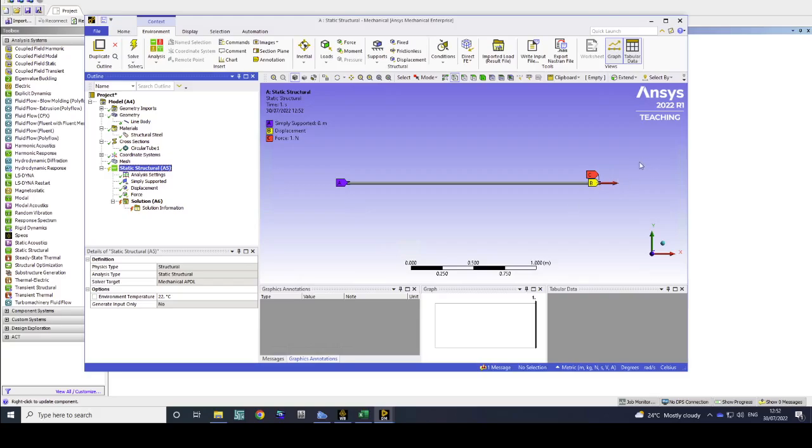The other thing is that you may wonder why this is not putting the beam in compression. Again, fine, when you do the buckling analysis, the sign will tell you if the load should be positive like this or should be negative, hence in compression. Okay. If I run this simulation, you will see that it will not succeed.